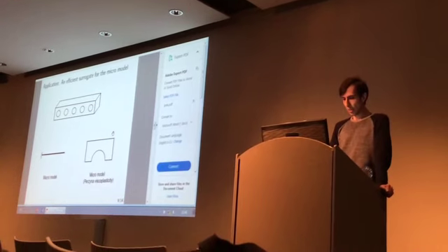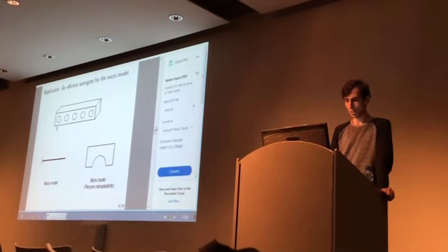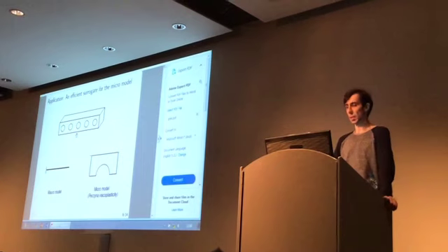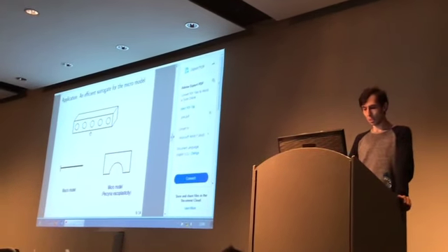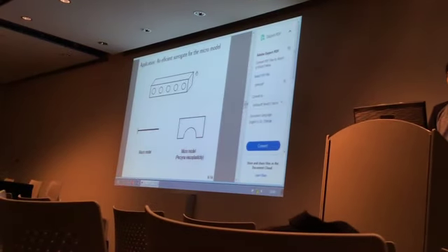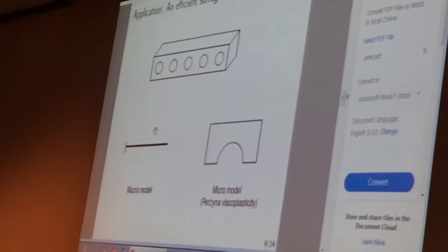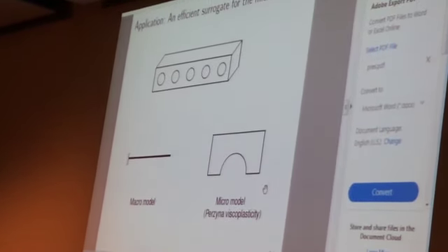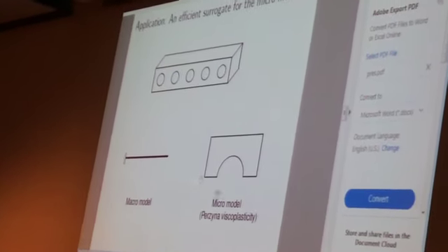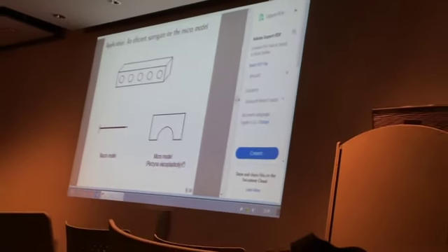Now let's go to the application of some results. Consider this object here. It's a bar. There are holes along its length. The holes penetrate all the way through its width. I assume that the length of this bar is significantly larger than its width and height. So I can model it as a one-dimensional object. And to incorporate the effect of the holes, I will consider an FE squared scheme with micro model like this. And for material class, I use Perzyna viscoplasticity.